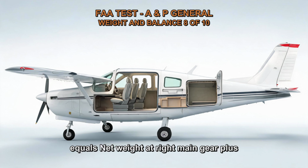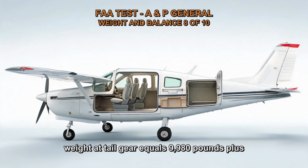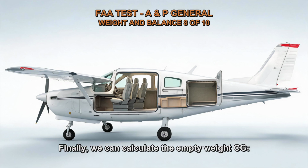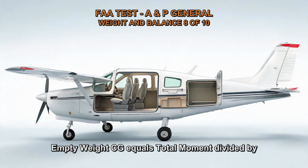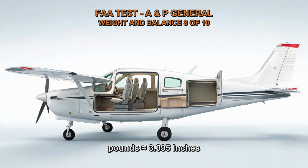Empty weight equals net weight at right main gear plus net weight at left main gear plus net weight at tail gear equals 9,980 pounds plus 9,770 pounds plus 1,970 pounds equals 21,720 pounds. Finally, we can calculate the empty weight CG. Empty weight CG equals total moment divided by empty weight equals 67,272 inch-pounds divided by 21,720 pounds, which is almost equal to 3.095 inches.